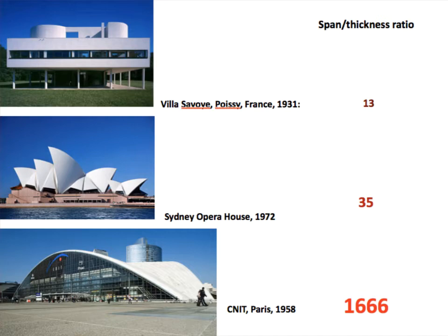The better performance of the Sydney Opera House shell is due principally to its overall form producing internal forces that are combinations of bending and axial force, which reduces the amount of bending that is present. Both of these structures have elements with solid cross-sections, which is an inefficient configuration for the resistance of the bending type of internal force that dominates their responses to load.